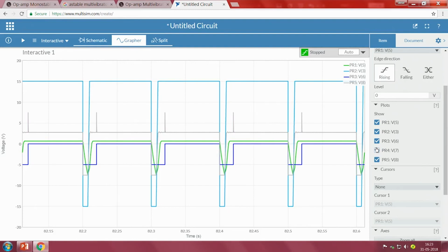Now I do not need it, but we can observe one thing: when I give a spike, the negative voltage is somewhere around 664 millivolts, which is almost equal to the 0.7 volt diode cut-in voltage, right. Whenever I give a negative spike, the blue color one is a negative spike for somewhere around 10 milliseconds, right. Since it is passed to a differentiator, it has generated one positive spike of 10 milliseconds, sorry, it generated a negative spike.